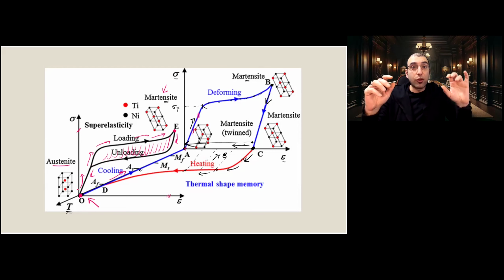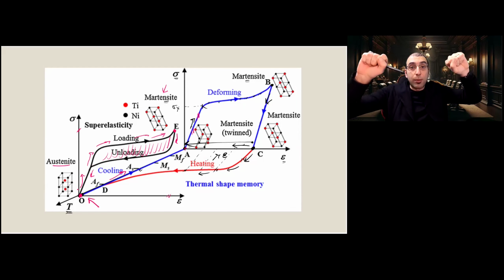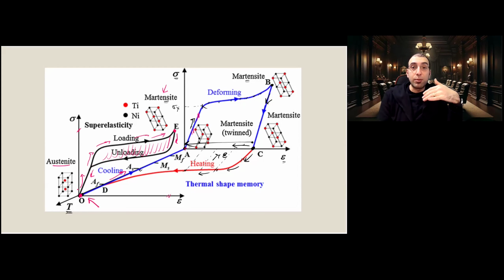And plastic deformation can be much more than elastic deformation. So when you do it above AF and you are applying it like that, if you let go, just like a spring, it will go back by itself. So that's the difference between shape memory effect and pseudoelasticity.